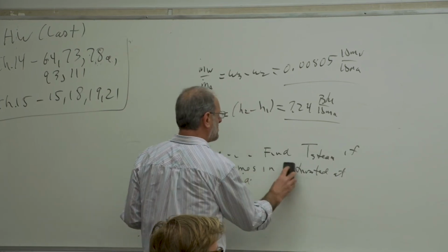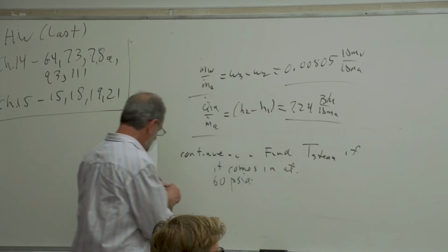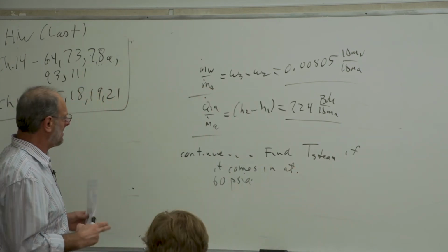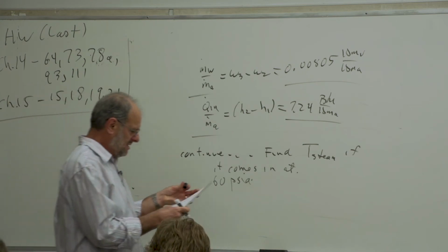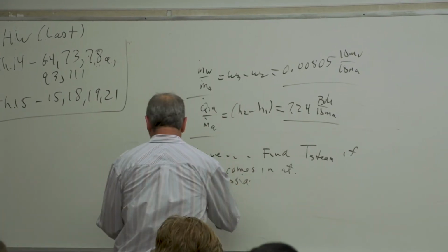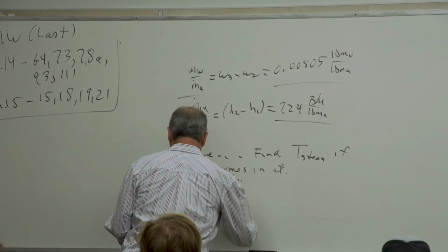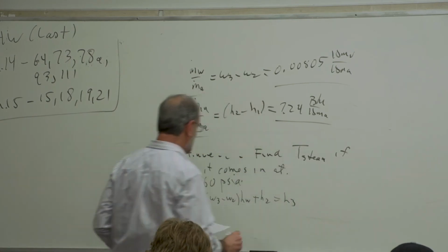In fact, I shouldn't say saturated. I'm just going to say it comes in at 60 psi. We don't really know if it's saturated in this particular case. All right, so how do we do that? Well, we have to go to the third of those equations that was derived just a few minutes ago. (omega 3 - omega 2) HW + H2 = H3.